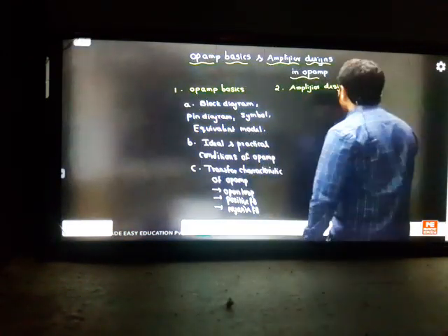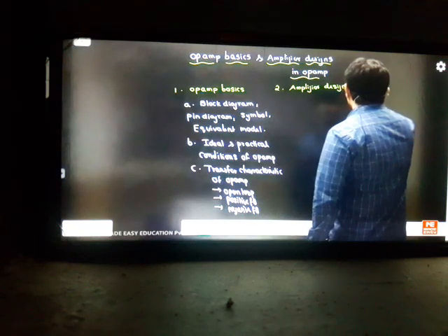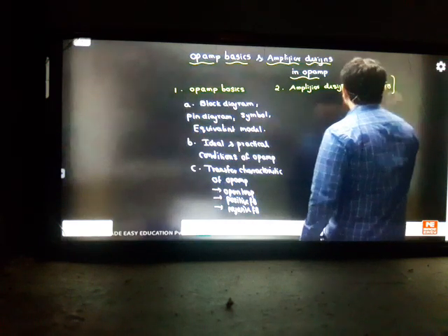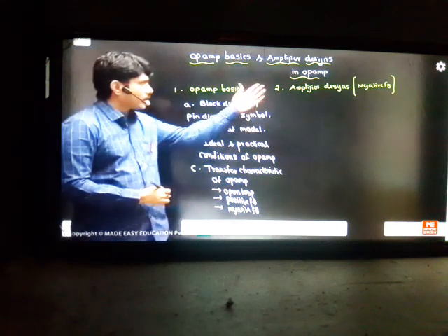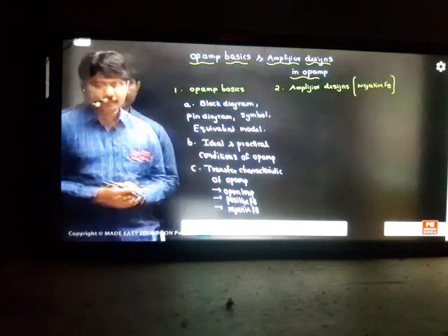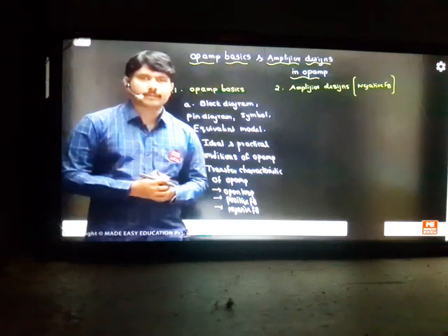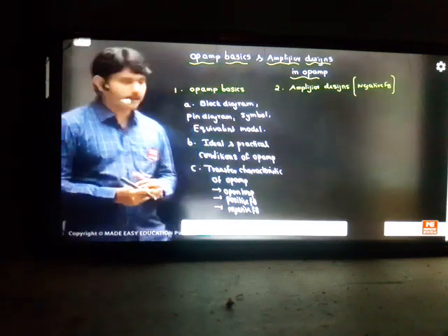That's why whenever you hear the words amplifier designs, keep in mind we are going to design all the op-amp circuits with the negative feedback concept. So first we are trying to learn negative feedback in all classes. After that, slowly we will enter into positive feedback and open loop systems. We don't want to use positive feedback or open loop, because to get more stability for amplifiers, negative feedback is preferred compared to open loop or positive feedback.